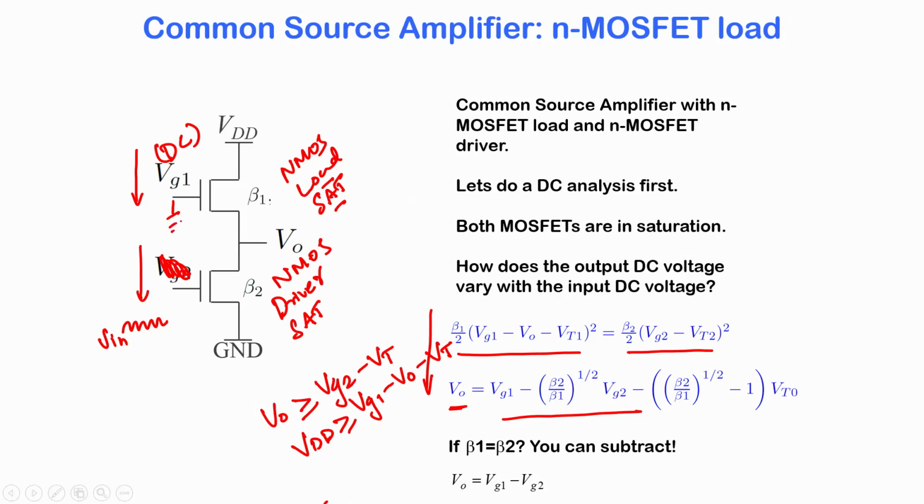So, let us take this case, and why have we chosen an n-MOS device? The hope is that the n-MOS device can be engineered through aspect ratio, through applying VG1 in a suitable manner, and so on, to make sure that V out is always kept finite and the driver MOSFET is kept in saturation, unlike the case of using a resistor. We hope that this is going to give us large gain, because now we can use many more parameters to tune the resistance of the MOSFET, but let us see whether that works out.